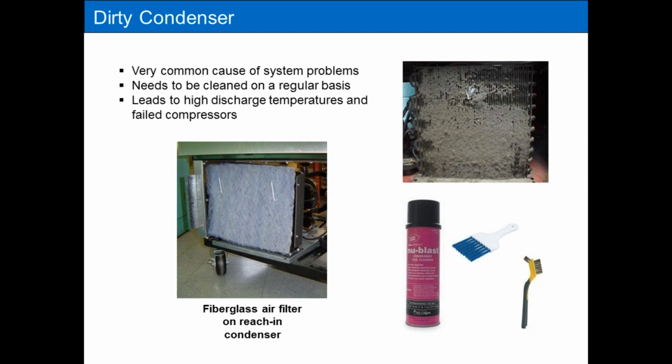Does it affect the airflow? Honestly, I don't know. I've seen them on units where I started doing maintenance, and other companies had been using them in the past. I've left them on, and I personally have not had problems with having them on, but I don't know that for a fact. If you guys know for a fact, or you have data showing they're good or not, maybe at the end of this presentation you can send us a comment about that, because I've used them and not used them. They're out there. Ice machine manufacturers use them all the time, so that's pretty common on ice machines, to have these filters on their condensers. But on reach-ins and coolers, I've seen them added on by techs.